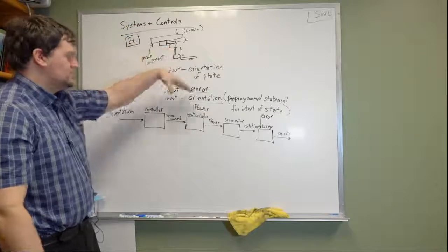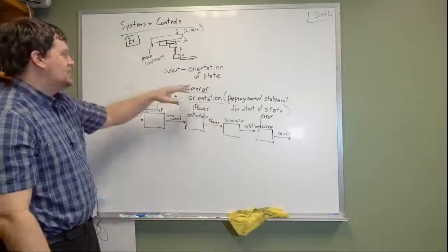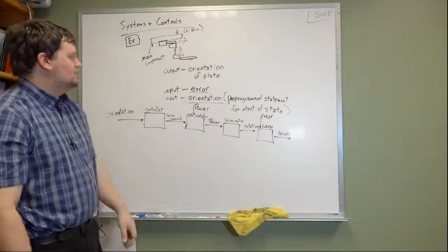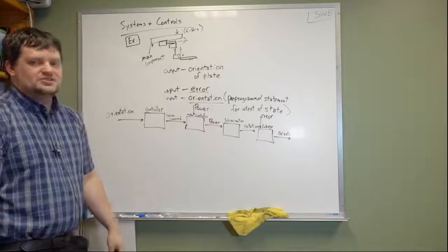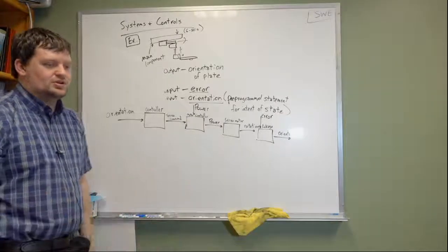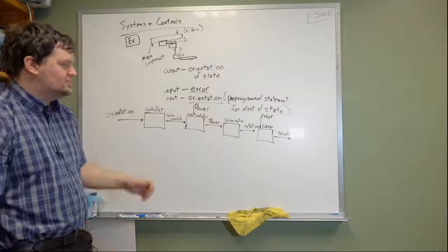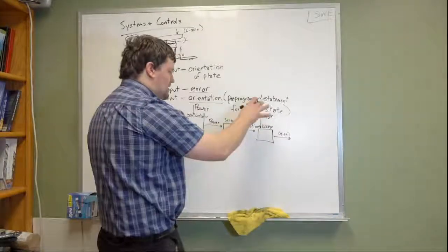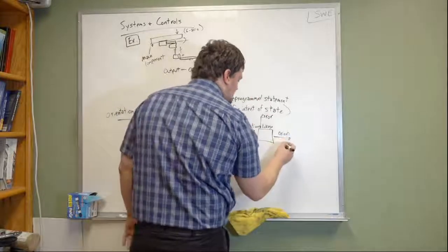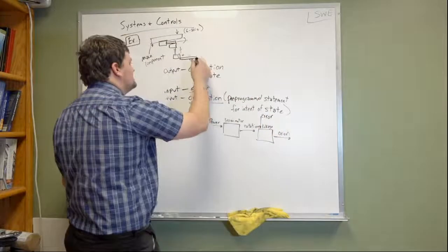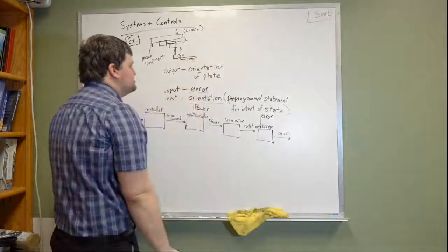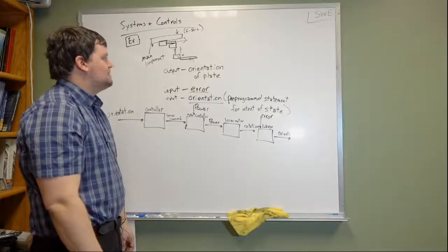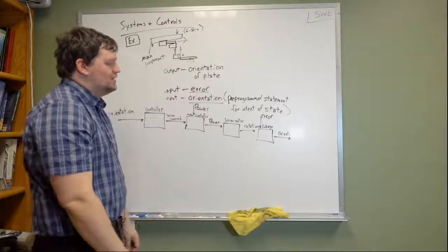How does the linkage orientation change? And how does that then sum with the rotation of each of these joints to procure a position for that motor? But you have the error coming into the linkage, and what we end up doing here is we have this rate gyro that's placed on top of that plate, well, on the bottom of that plate.